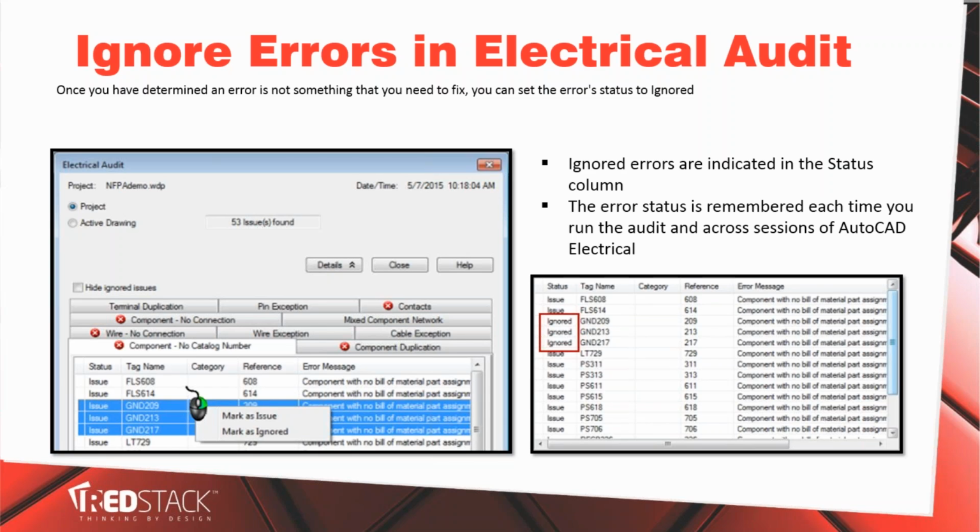Okay, I do use it, but not that often back in the old days. One of the reasons I don't use it that much back in the old days is because it's too much false alarm. For example, component with no connection or wire with no connection. These kinds of checks had a very high probability of a false alarm because some component, like 3 switches, and you only connected 2, right? Or it has 5 inputs and outputs, you only use 3. Then it will report that that component has no connection because we haven't connected the other 2 yet. So that's kind of false alarm, right?